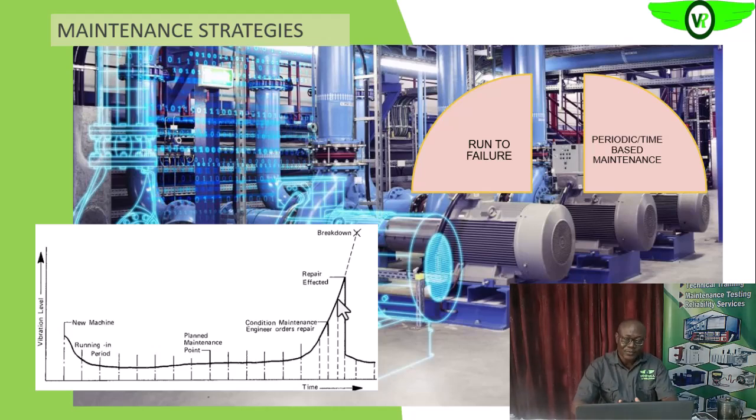So the idea of preventive maintenance, or time-based or periodic maintenance, which is what we have here, is based on the fact that before it gets into this region, or as it is getting into this wear out region, before it eventually fails, we should do something. We should change out that component to bring the curve back down to its normal operating region.